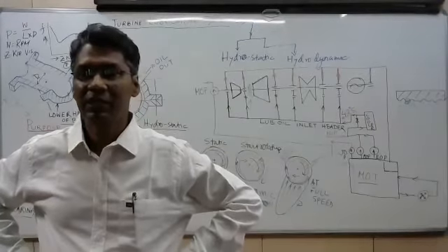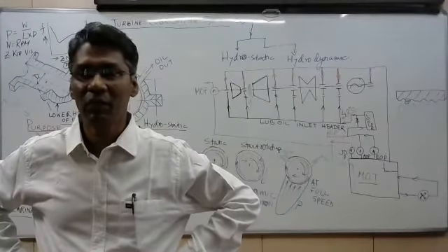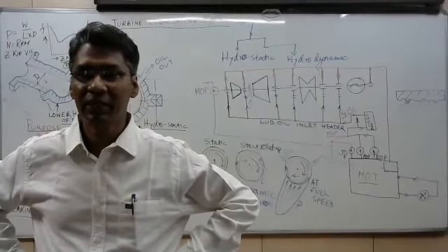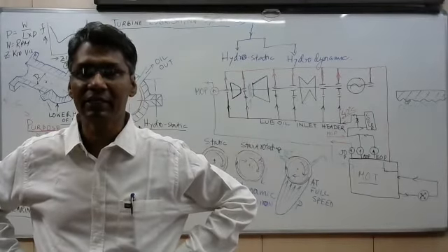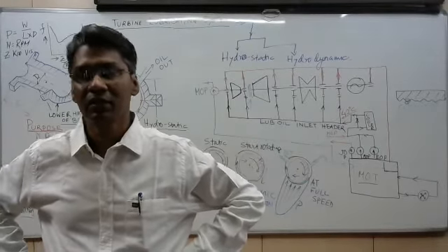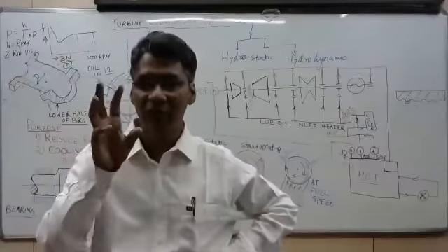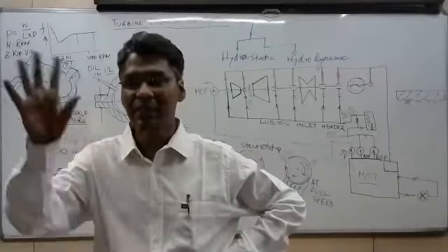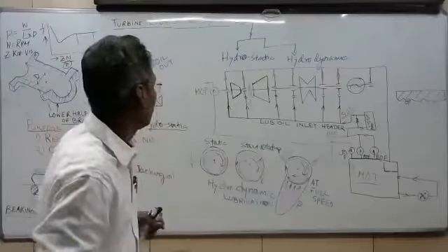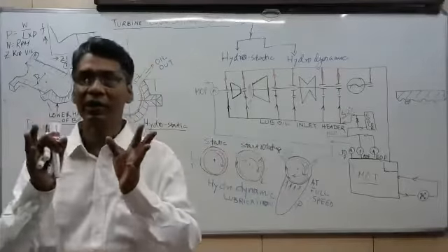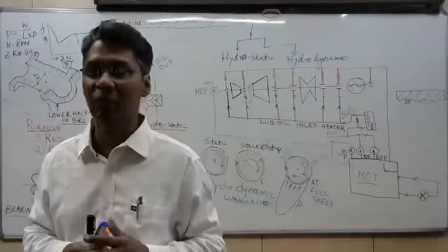Sir, I mean to ask, the lube oil pressure is becoming lower than the design pressure during turbine running condition. What may be the reason? In running condition, we are providing oil for hydrodynamic lubrication and cooling. Pressure is not important; pressure means we are allowing some amount of oil. The quantity is important in that case.